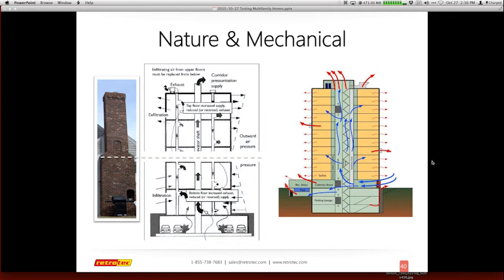Here's another one that's trying to show what happens when you have various pressures when you're doing the test itself. It's hard to see, but right down here at the bottom, we have our set of blower doors, and they're trying to pressurize the entire structure. Then I can try and do a measurement or confirm what my total leakage is. So this is a total structure type of test. Some people may be doing this with multifamily. Again, it's not that common from our understanding.